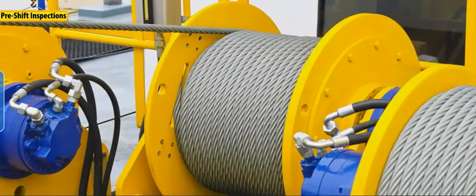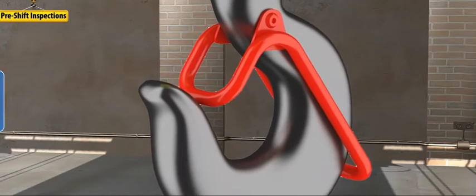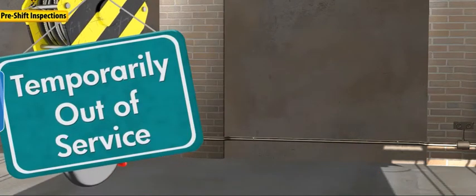Check the way the cable is winding onto the drum. It should wrap straight without overlapping itself. The safety latch should open and close the right way, and if the hook is bent open or twisted, get a new one. If you find anything wrong with the crane or any of its pieces, tell your supervisor and take the crane out of service until it's fixed.